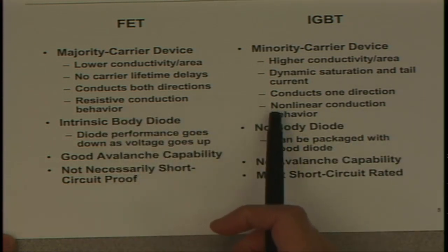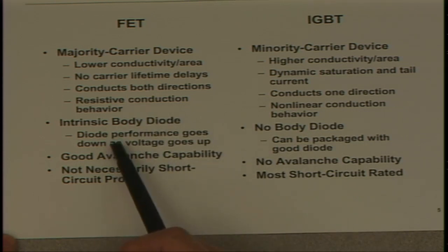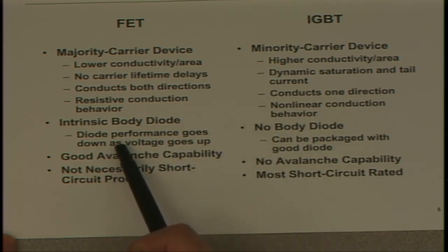Resistive versus nonlinear conduction behavior. The intrinsic body diode in the FET. So, you're familiar with that, I presume. It can be very good at low voltage. A 20, 30, 40 volt FET has an excellent dynamic body diode characteristic.